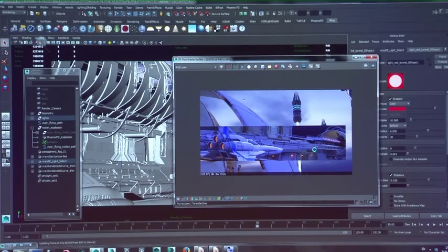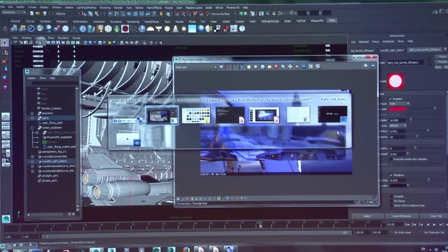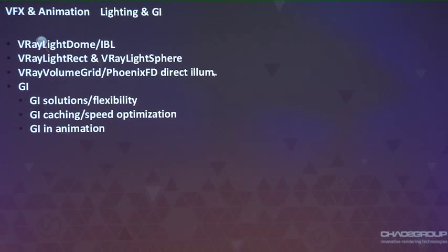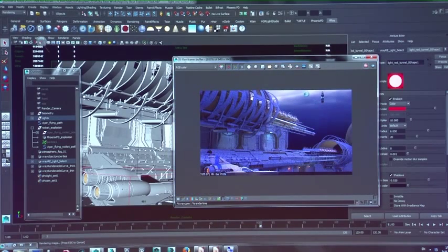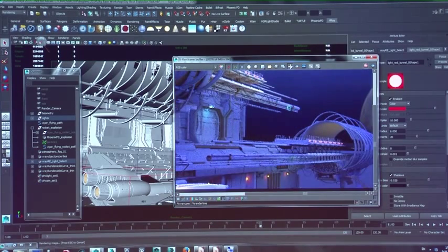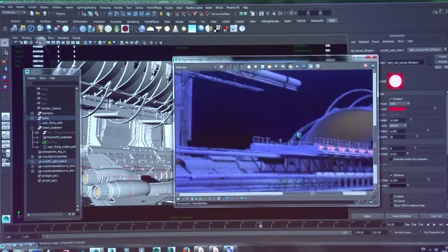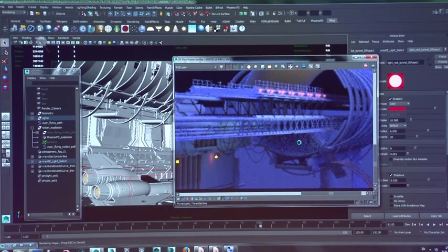So while this is rendering, okay, so I mentioned the direct illumination thing. By the way, a new feature of V-Ray 3.0 is this one, track mouse while rendering in the progressive mode, which will force the samples to where, for example, when I see that here is a little bit noisy, I can just place my mouse over there and all the computing power is going to be focused on that part.